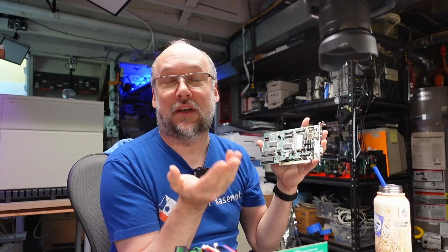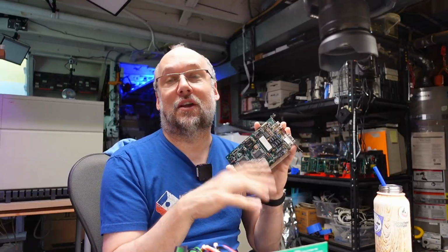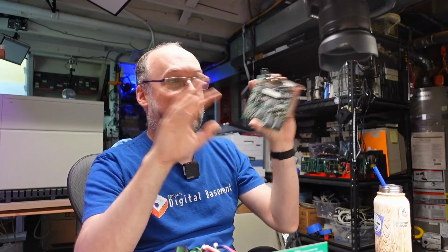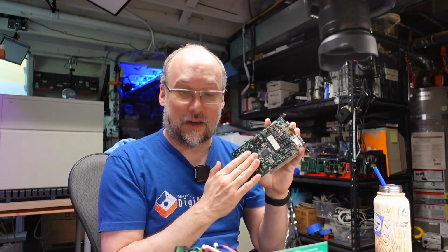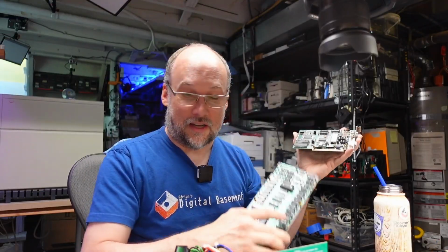And because it doesn't have any snow, there's no ugly artifacts, and that's actually a really good compromise. Now, remember when I turn on the computer with this card in there, you see that kind of weird flashing, corrupted garbage? When you have a real CRT hooked up, you also get a totally unsynchronized picture until the BIOS initializes the video card. And that does not happen on the CGA card here because I think that bit starts out as 0, low, which has the effect of disabling the video output. And only once the BIOS initializes the video card does it bring bit 3 high, which turns on the picture.